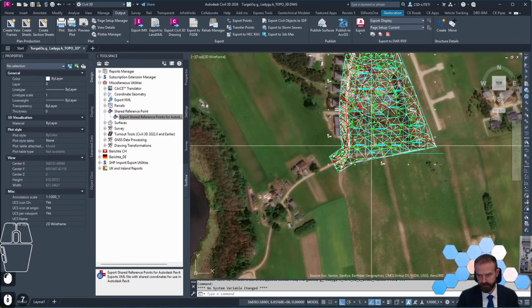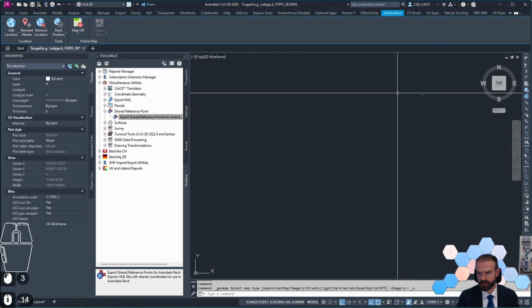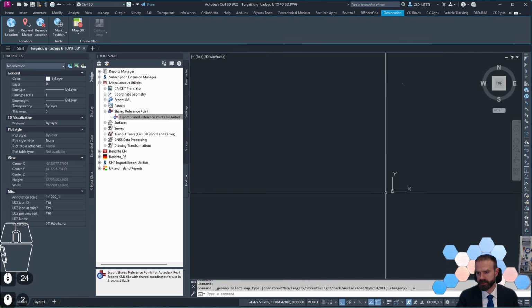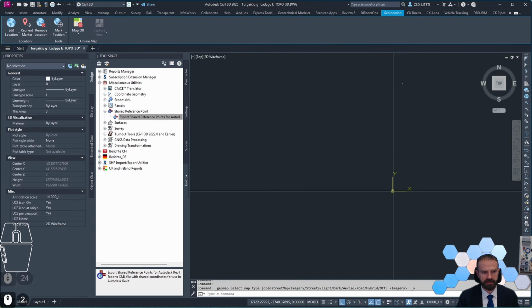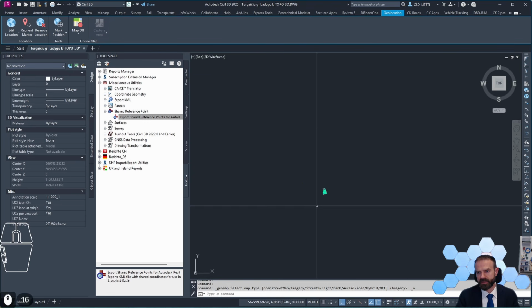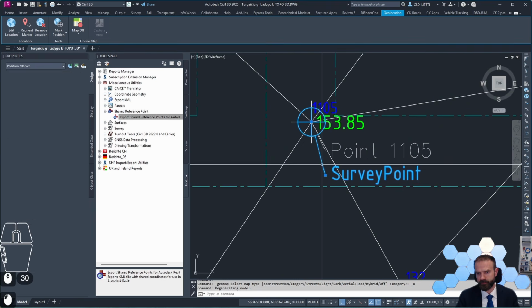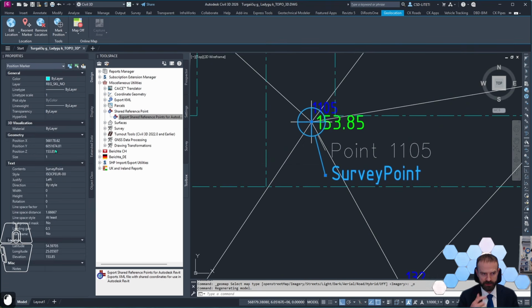So if I go to the CAD file and zoom out, my internal origin point is located here. So I cannot link using the internal origin point because my internal origin point is together with the base point and survey point. So I set up coordinates of this point for my project.